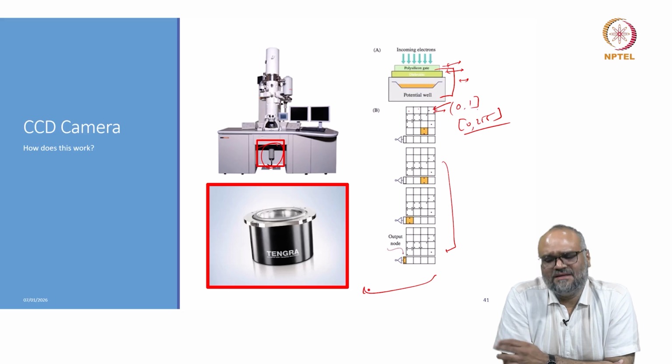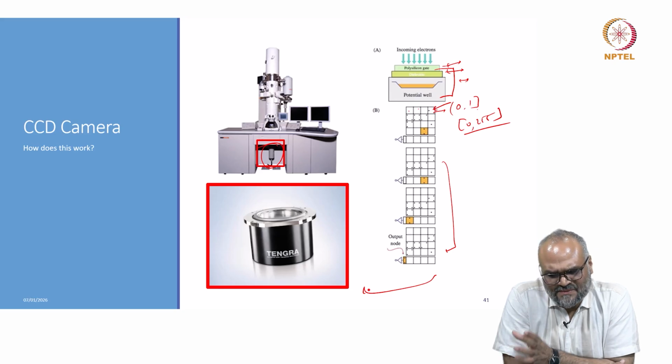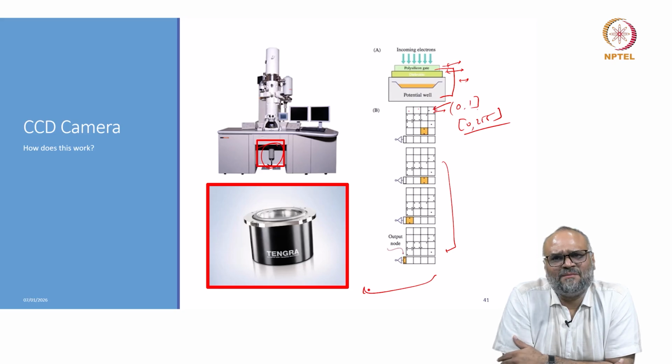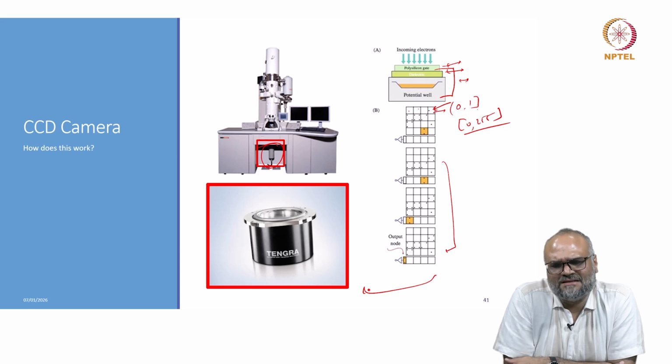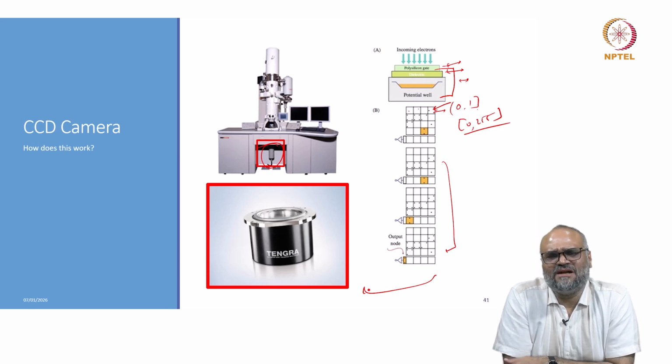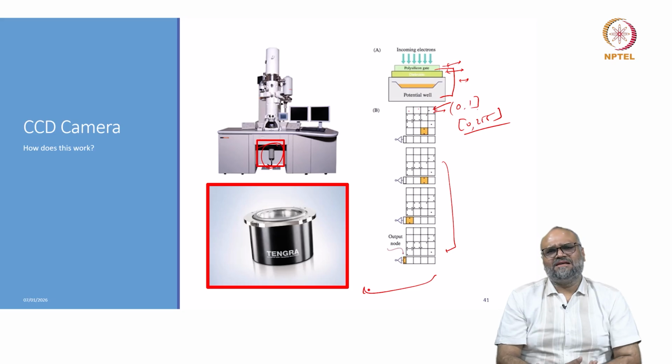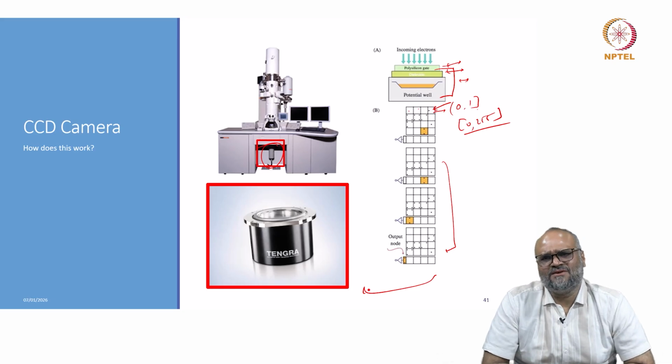So the quality of images that you were recording on CCD cameras was quite good, but the frame rates were quite restricted. You typically had frame rates of something like 2 or 3 frames per second in the best case scenario, to about 20 or 30 frames per second. But nowadays, with the CMOS kind of cameras, you can also achieve easily 200 to 300 frames per second.